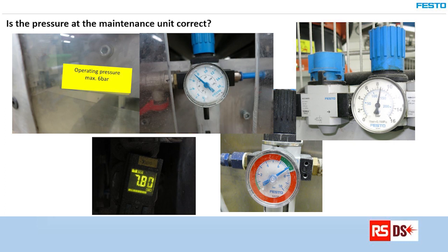What definitely increases with a higher pressure is the consumption, because higher pressure means more volume flowing into the machine. And so we try to decrease the pressure if we see a machine running with 7 bar to 6.5 bar, maybe to 6 bar, if possible to 5.5 bar. And see, okay, what is the performance? What is the speed of the machine?